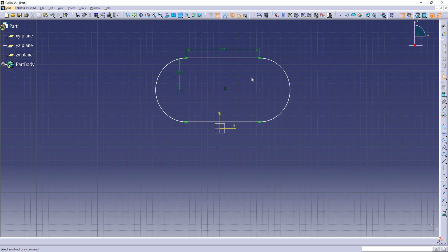What happens if I define the radius of the semicircle? To do that, I'll go to the constraint and click one of the semicircles. Oh, look at here. Some of the dimensions are over constrained. And I hope you know why it is over constrained. Press the escape key.